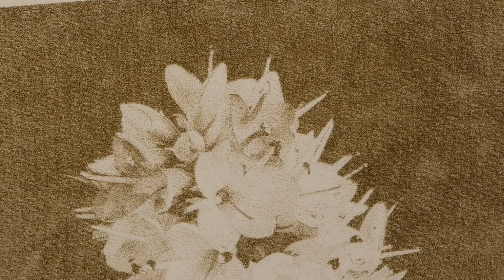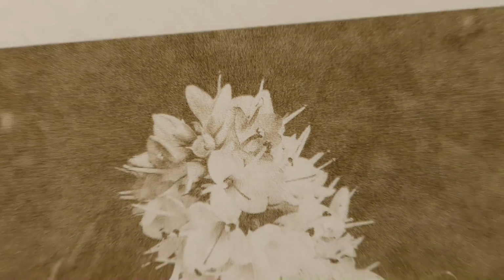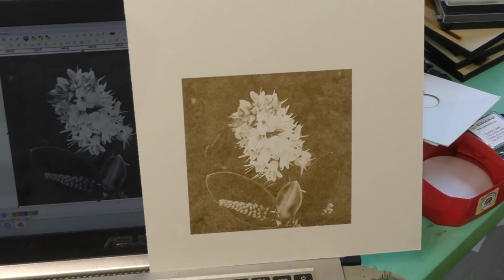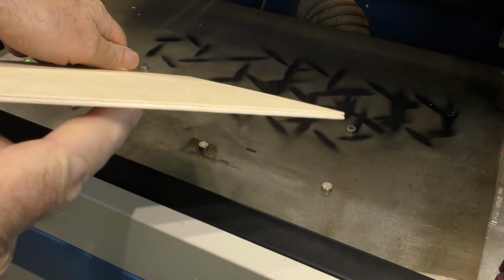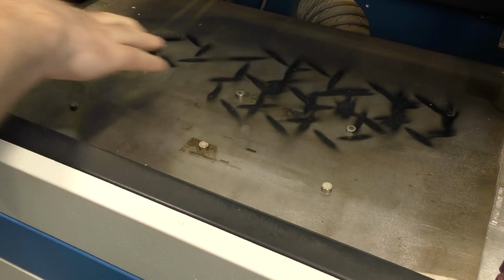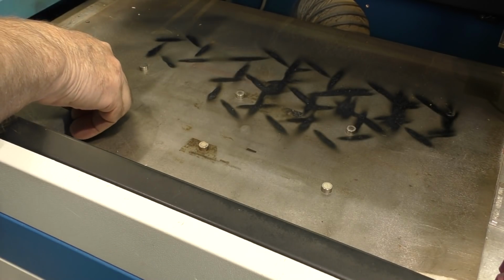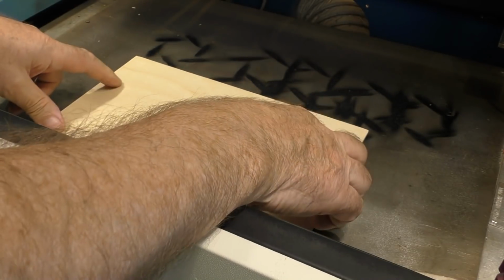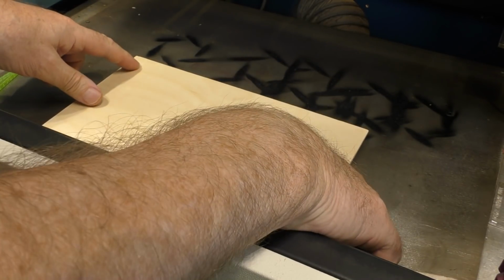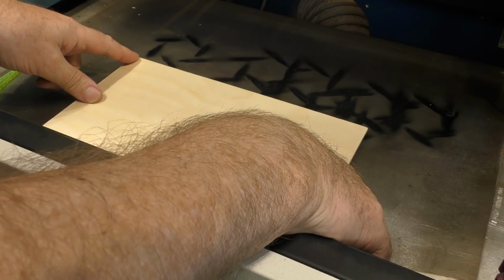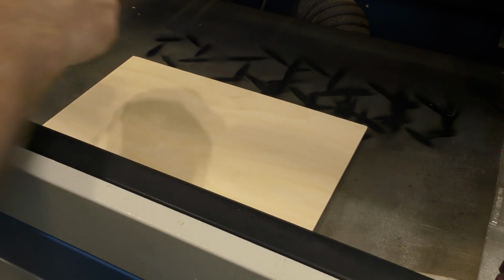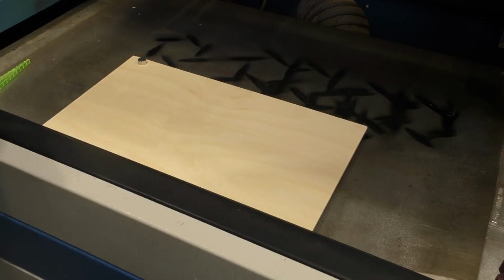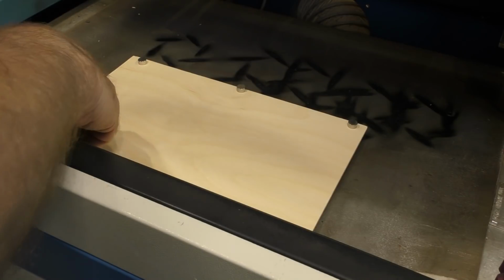Now we'll try the same thing on wood, because wood has got completely different properties to this beer mat card. Now, as I mentioned to you before, when I do this thin 3mm plywood, I put magnets on my table like this. So I've got 9 magnets on here, and I'm going to drop the board on here. And this particular board is actually not too bad. Some of them are quite badly warped, but this little trick here with a magnet on top and a magnet underneath fixes the problem.